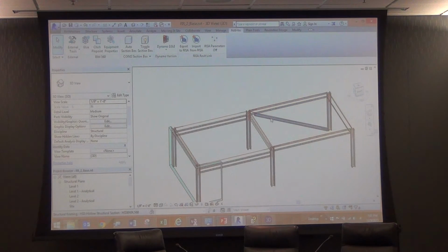Ideally that would take care of the problem that you were having, maybe? Yeah, well, the other issue is that roofs will be sloped. Will that still solve that problem? So let's see here. You wouldn't be able to set it to level 2. Right, that's where we break it every time. Maybe the grid lines are at certain elevations, so we can set those, but then you'll have a joist that lands in between two columns at some random dimension.